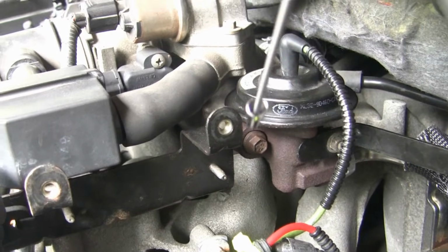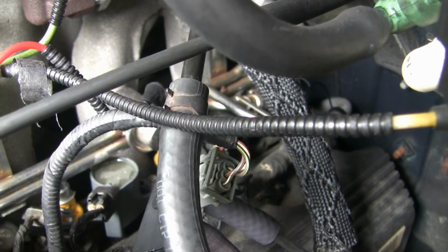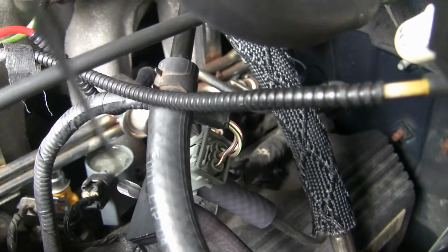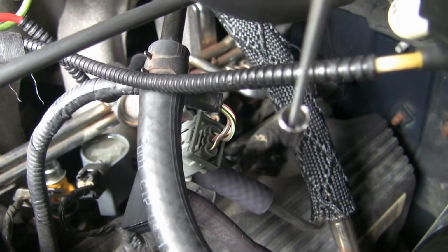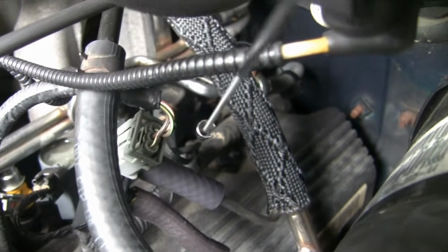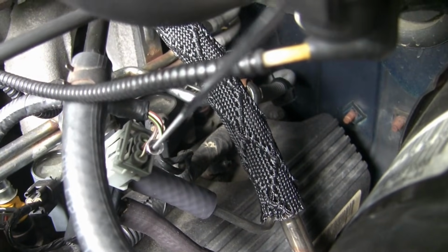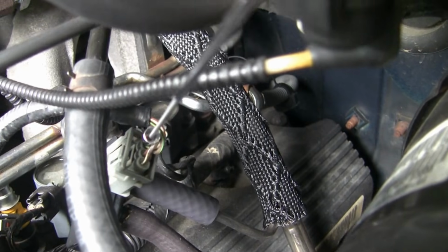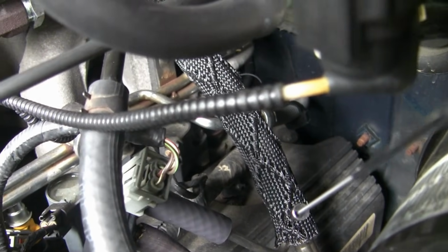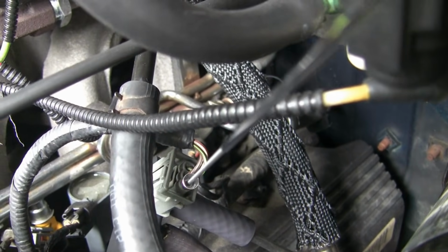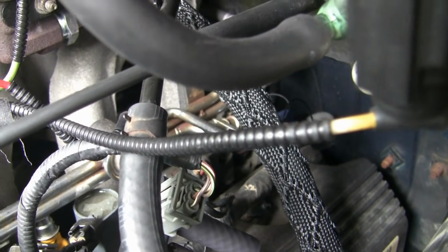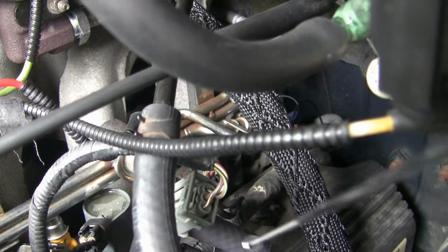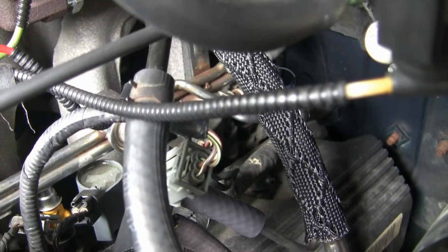So some of the things you want to look for in the troubleshooting process is, they say typically on these engines, 9 times out of 10 the DPFE sensor has failed. And really, to test it, you either need to have a computer interface. There's 3 wires down here, and I believe the center one is the ground. One of the other 2 is a 5-volt reference. And then the other one is the 0 to 5 volt signal, and that's the signal that gets sent back to the computer. So you'd have to be able to monitor that with a voltmeter or a computer interface.